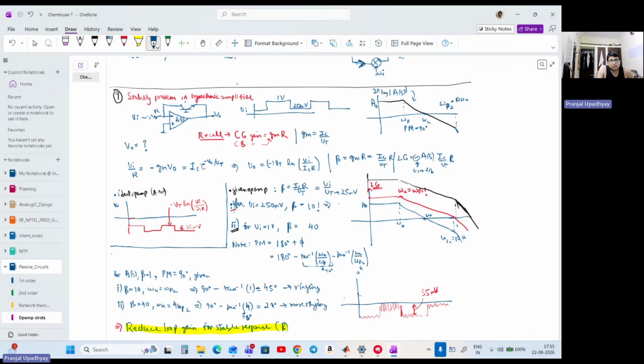in basically common base configuration. Now, the exponential characteristic of this BJT is why we are getting this logarithmic behavior to begin with. We could also have a diode here actually, and if we cleverly place some diodes over here, then also, since they have exponential current, it won't be exactly just a diode in feedback, it will be a clever arrangement of diodes so that we can bring about again a natural log behavior of output with respect to